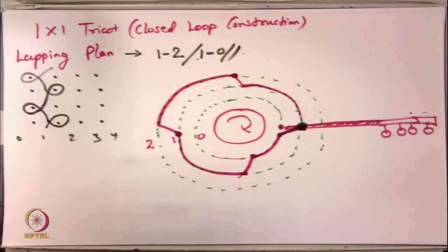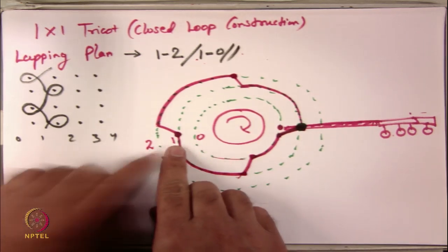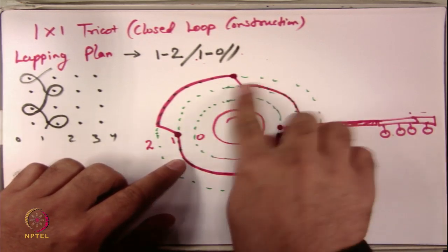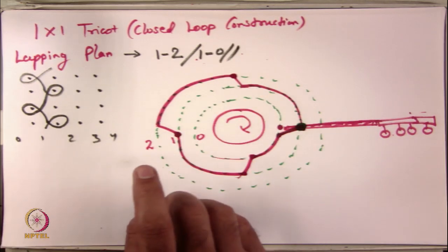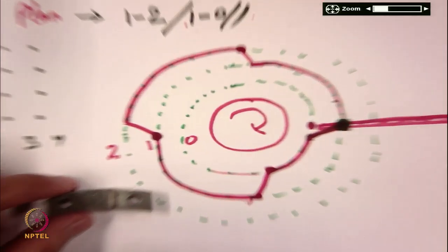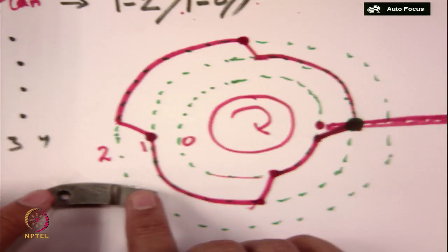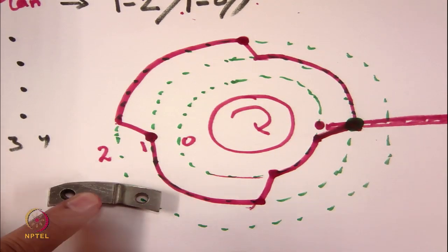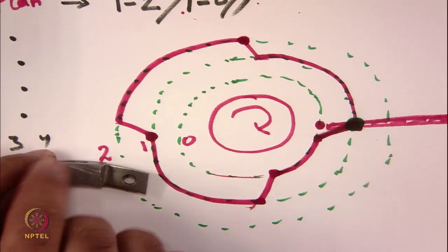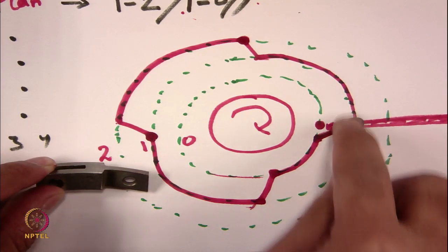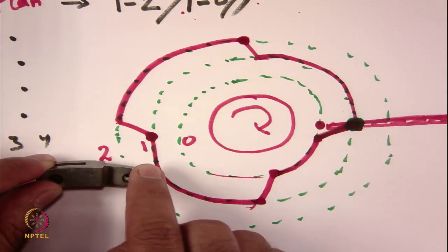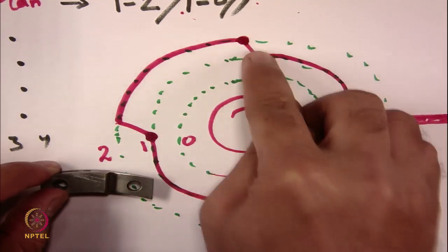How do we actually create this profile? So, first of all, out of the 3 links which I showed you, it has to first interact with the first link. Okay. So, the first link I have chosen the middle height. So, this is the middle height and the profile is of certain height. So, this distance the follower will move without doing anything. After that it has to jump.